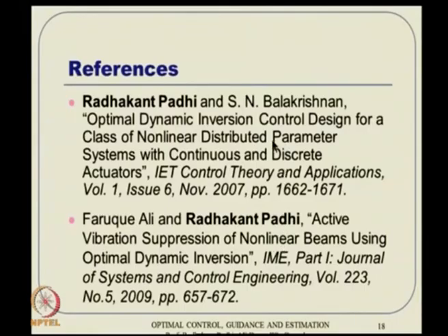Remember that the difference is, if you talk about something like heat dissipation or stable system dynamics, fluid flow or heat dissipation like that, these problems are relatively easier. They are something like parabolic differential equations. But when you go to vibration, these are typically elliptic or hyperbolic differential equations. They don't die out so easily. They will continue to vibrate unless there is a good amount of damping. So in that sense it becomes a more challenging problem. Okay. But anyway, we are bothered about the ideas here, so we will concentrate on the first one.